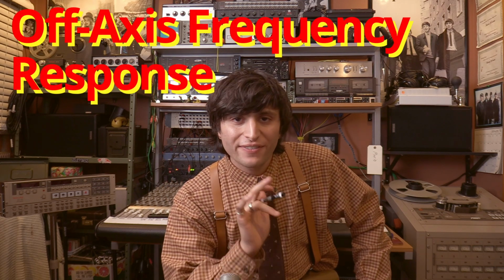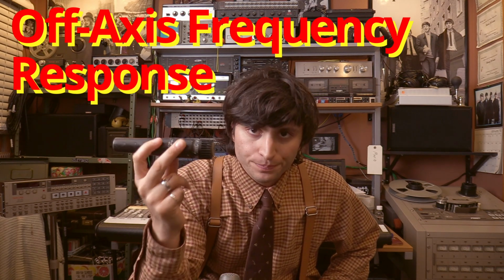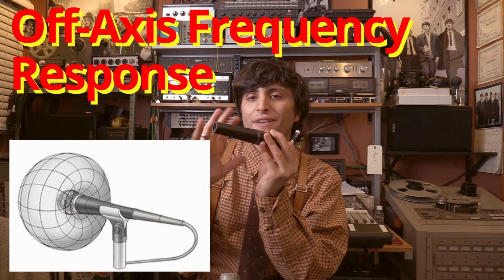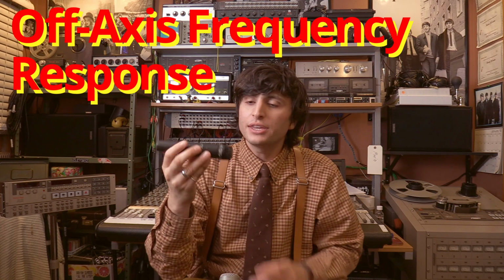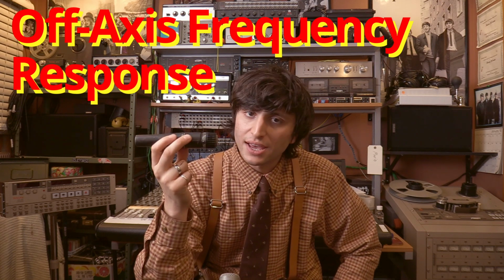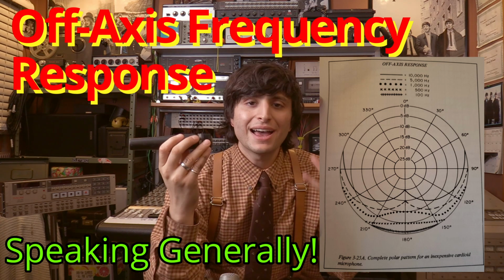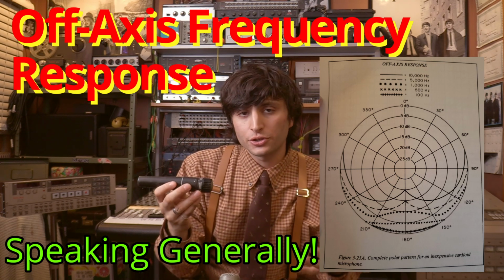Alright, so we're almost at the end of this video, but I need to mention two more effects that are seen with microphones. The first we're going to talk about is off-axis frequency response. Let's go back to the conversation about directionality in a microphone. In a cardioid microphone, if you remember, it is going to reject some sound coming from the off-axis directions. In actuality, due to the design limitations of microphones, the off-axis frequency response is going to change depending on the frequency of said wavelength. For higher frequencies, the cardioid pickup pattern is going to stay true, but as the frequencies drop, the cardioid pickup pattern is going to slowly turn into an omnidirectional pickup pattern.